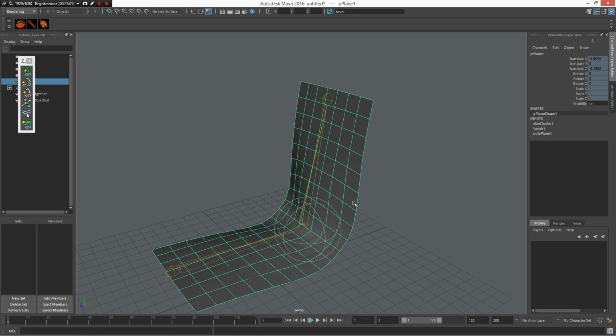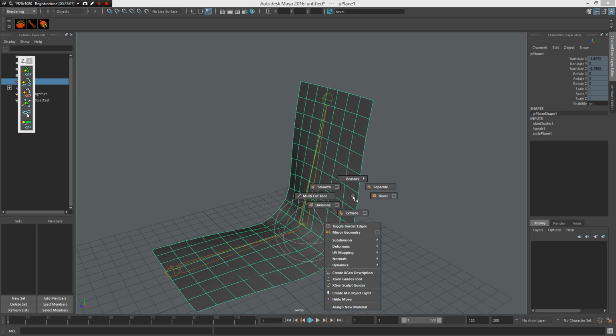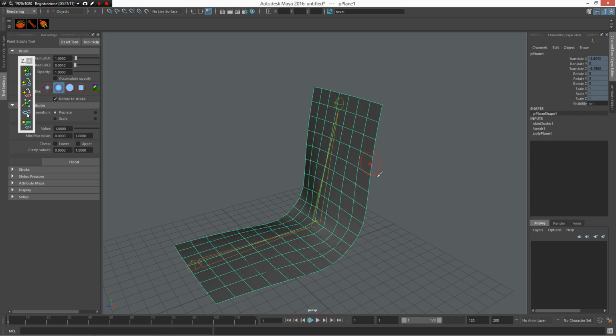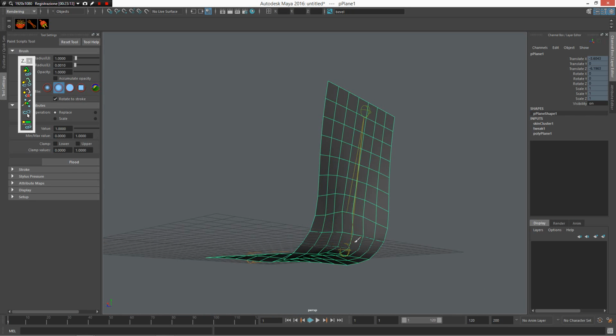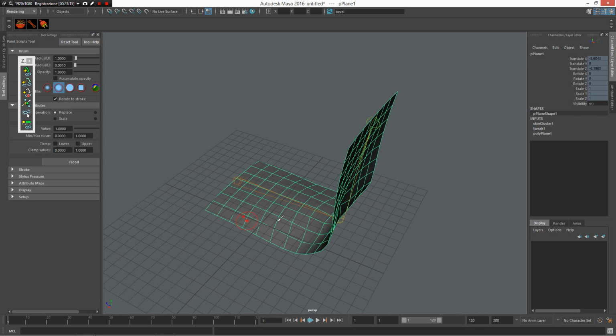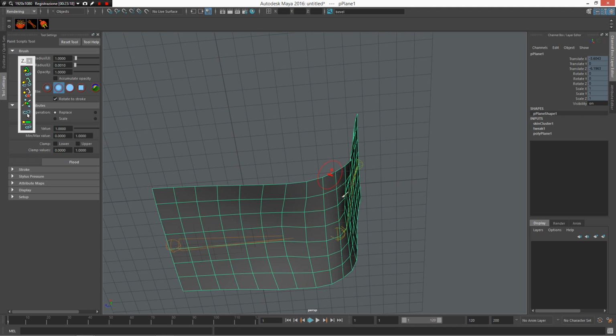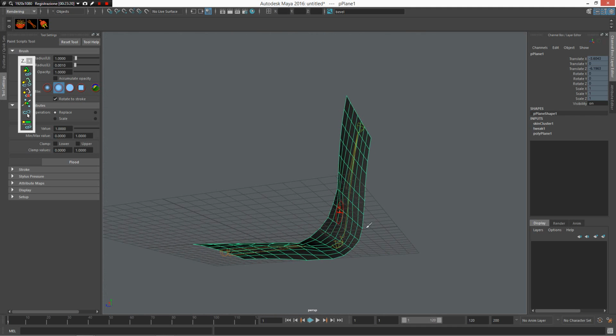new smoothing tool. So I can use my Z button, press the right mouse button, brushes, arrange skin weight, and now I can very fast, without selecting the joint in the hierarchy I want to use, smooth my skin.